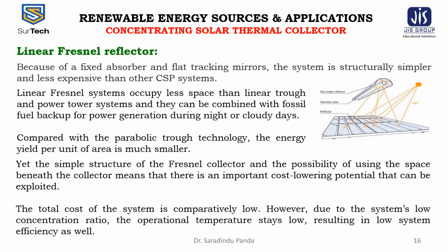The additional set of mirrors are also placed across the top of the tubes in order to capture and refocus any sunlight that does not directly hit the tubes. This configuration assures that all the available light is used. Depending on the position of the sun, the reflectors can be alternated at different receivers to improve the optical efficiency.